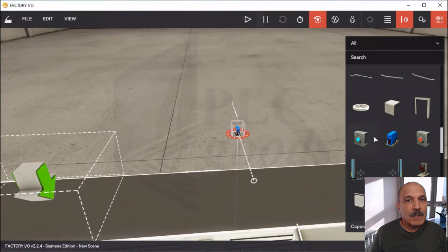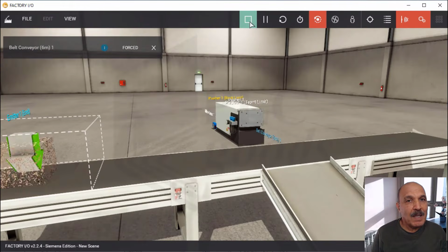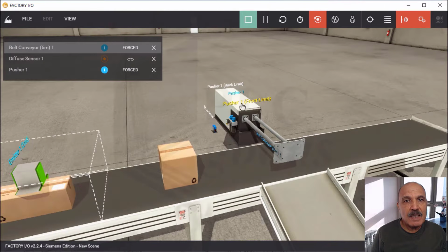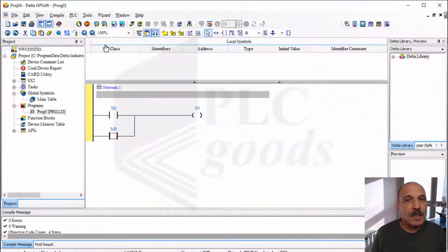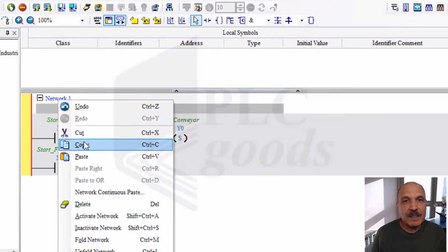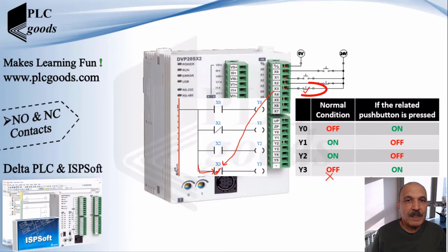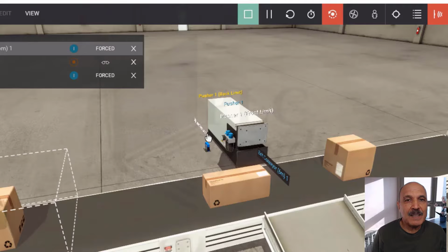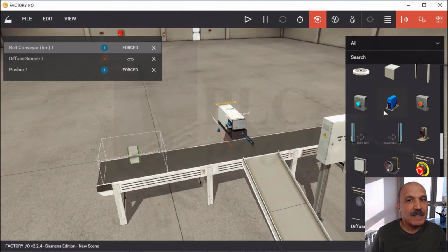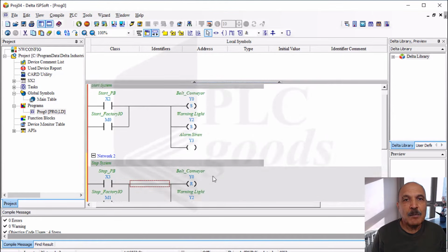The key steps include a primary system test, brief mentions of an OPC server, manual testing and adjustments, PLC program modifications, sensor integration, introduction of additional devices like a warning light and alarm siren, and the execution of a PLC program. Tags are defined for PLC addresses in the OPC server, and Factory I/O is configured to access these tags, enabling equipment control and monitoring.